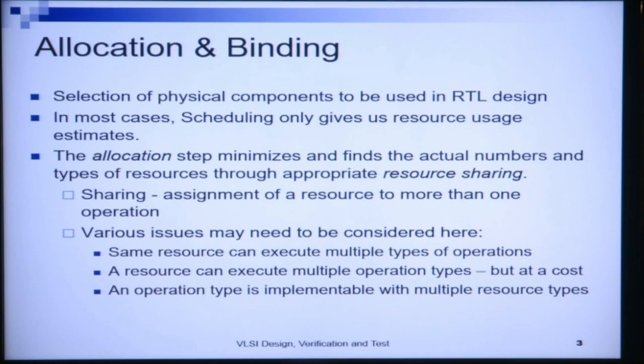Now, when we do resource sharing, we need to keep various issues in mind. For example, let us consider the case of functional units. The same functional unit can execute multiple types of operations, say. That means that in the scheduling step, we saw that the comparison operation, the plus operation and the minus operation were all being performed using the ALU.